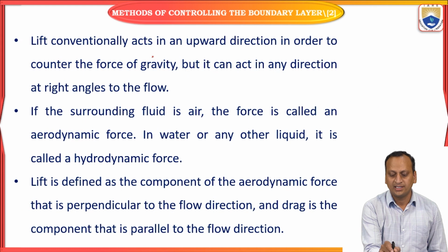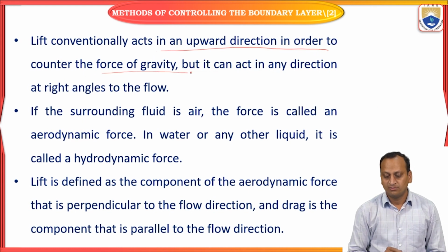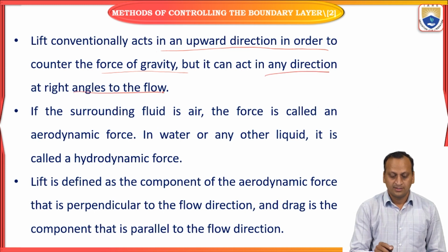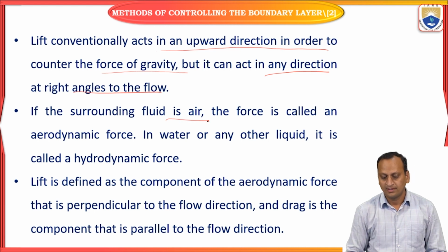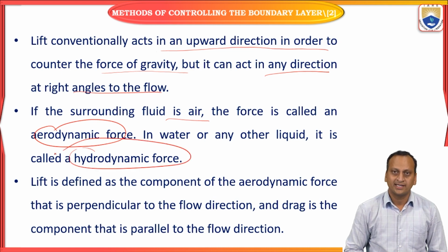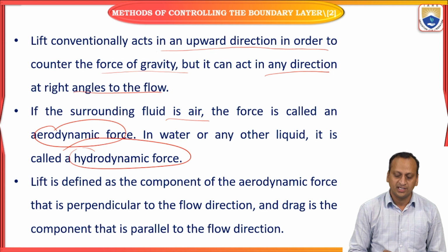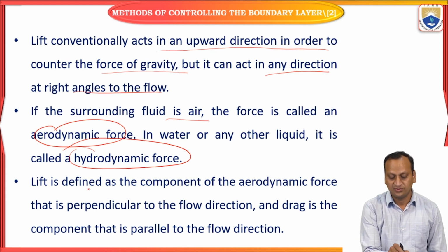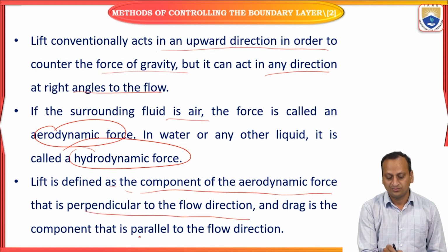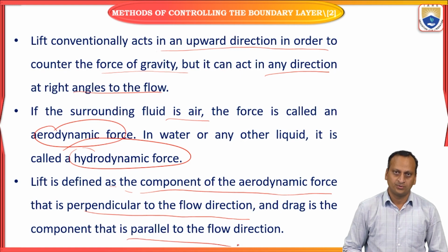A lift conventionally acts in an upward direction in order to counter the force of gravity. But it can act in any direction at right angles to the flow. If the surrounding fluid is air, the force is called the aerodynamic force. In water, it can be called the hydrodynamic force. So, in order to counteract the gravitational force, the lift will be acting in an upward direction. The lift is defined as the component of the aerodynamic force that is perpendicular to the flow direction, and the drag is the component of force that is parallel to the flow direction.